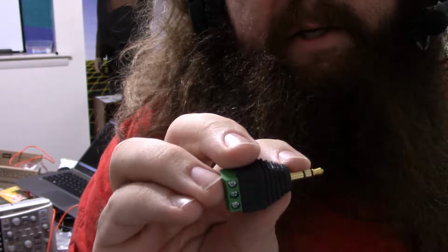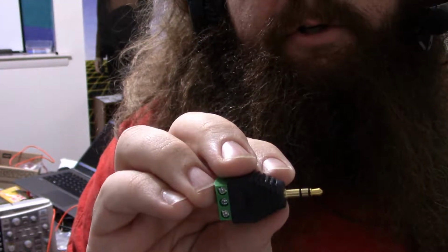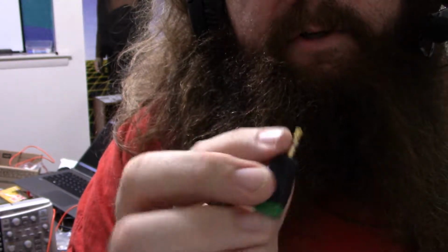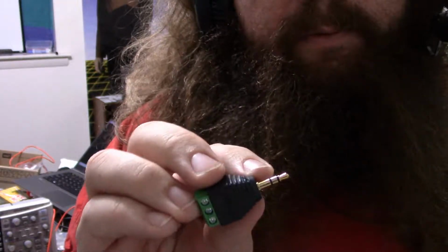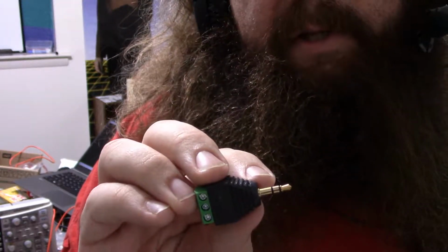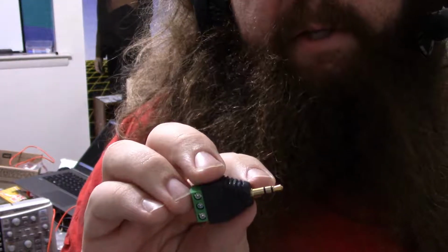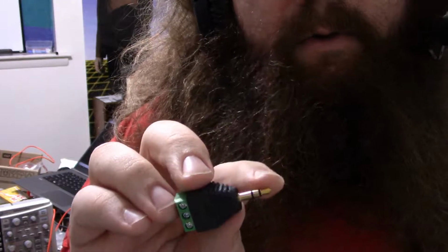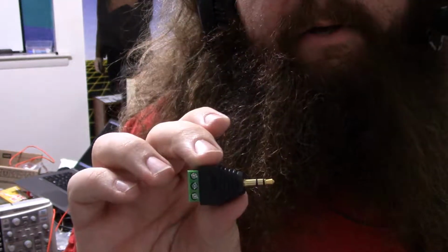If this black conductor here, the one further towards this end, is not there, you're shorting ground and one of the sides. You're straight up shorting them together just by plugging this in. And you have to believe people will make mistakes, or people will just do it on purpose. And you have to believe that you wouldn't let that fry your circuitry. And we're right. There is output impedance that prevents that. So if you plug a TS into a TRS, or a TRS into a TRRS, you're fine. See? There you go. So the good news is, I got the answers I needed.